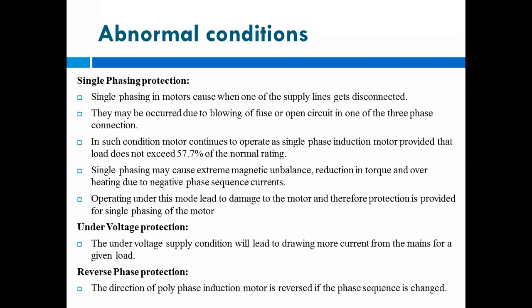Unbalancing is there because one phase is disconnected, so that's why the negative phase sequence currents will be there. Then operating in this mode leads to damage to the motor, and therefore protection is provided for single phasing of the motor.